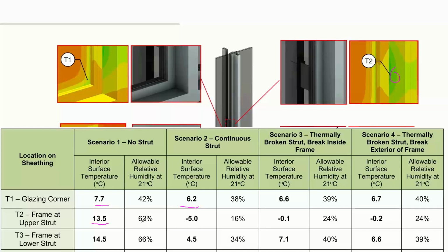So if we started with about 13 degrees, that's pretty high, that's pretty warm. All of a sudden, when you put that bracket in there, it drops down to a surface temperature of about -5 in this case for this particular building, and you essentially create these frost zones, and that's not something anybody wants on the interior of their building. So what can you do?